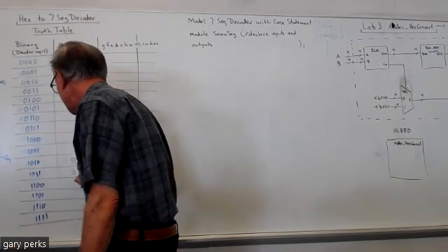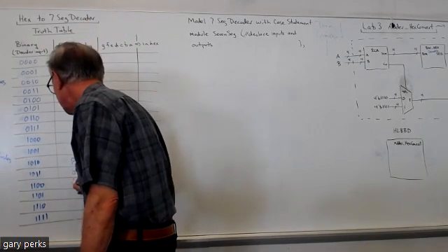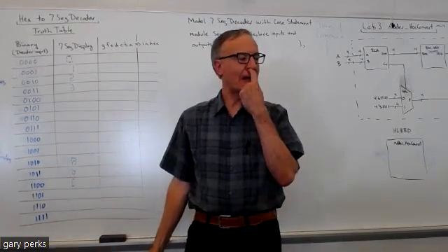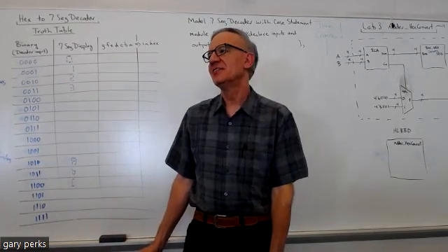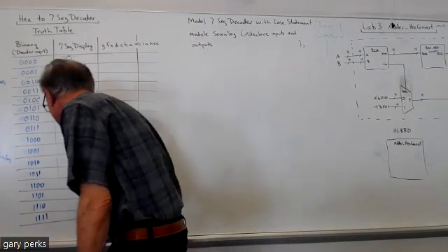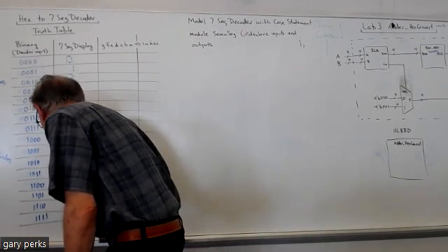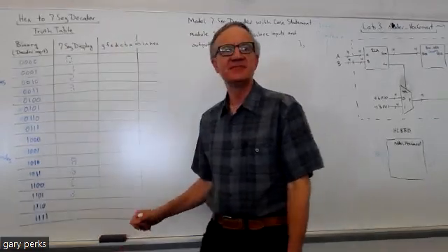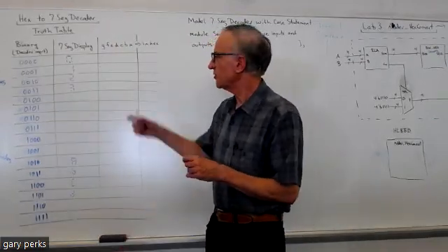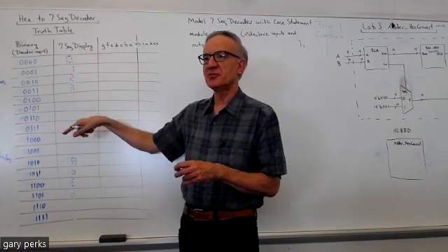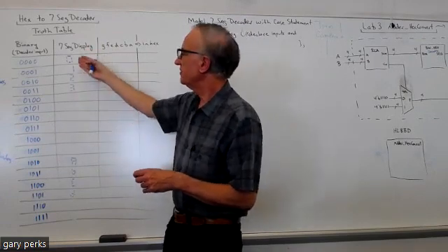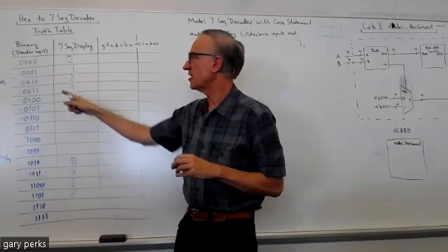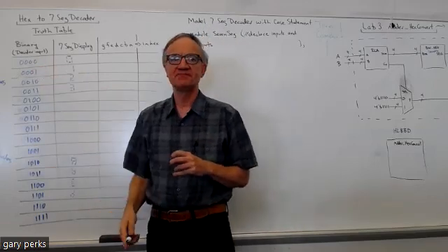Okay, but then uppercase C. See a problem with uppercase D? What's the problem with that? Looks like a 0. So you want a lowercase for that. All right, then you have a capital E, capital F. Right, so everybody see what I'm doing here? I'm just figuring out what segments have to light for each of the hex characters based on the corresponding binary.